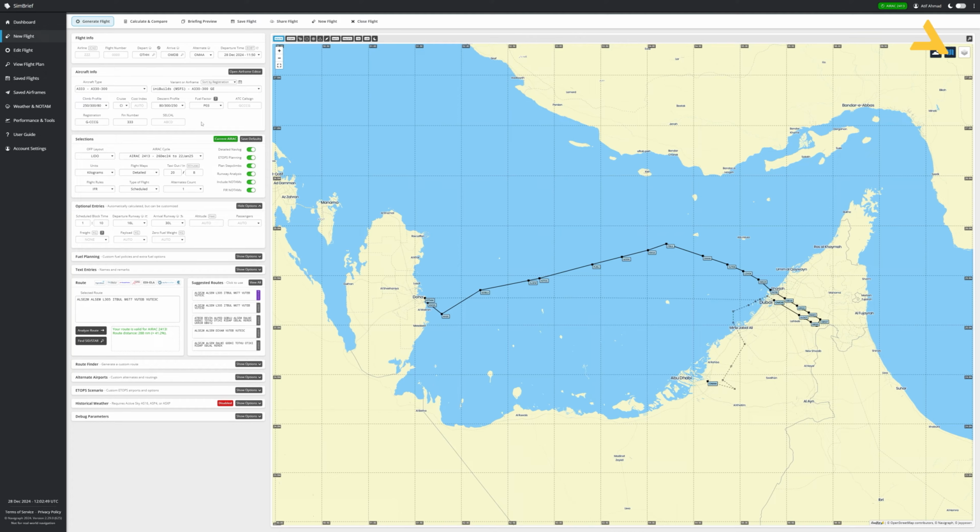The engine is GE, then the cost index. Now this is actually a number which determines how much fuel will be burnt during the flight. The higher the number, the more fuel is burned, the plane goes at a higher speed, but the range decreases.